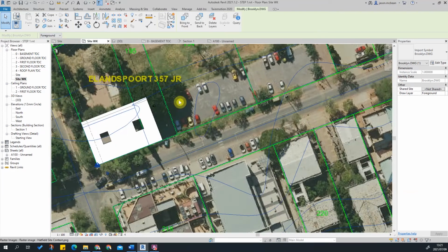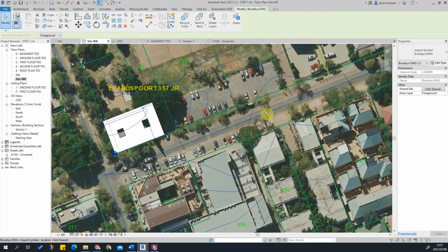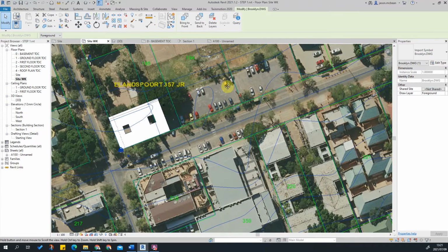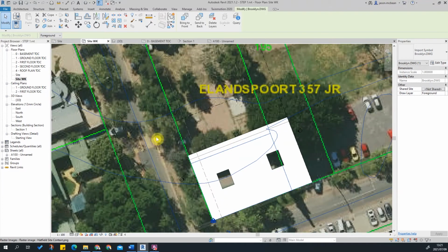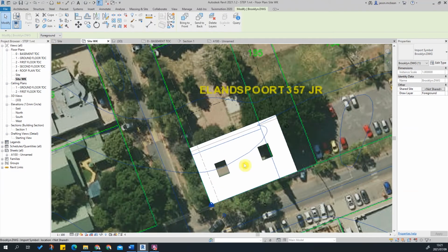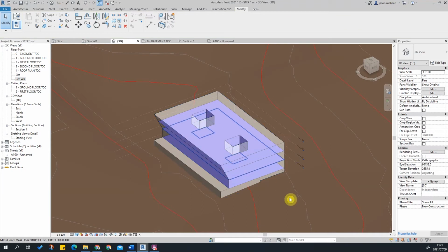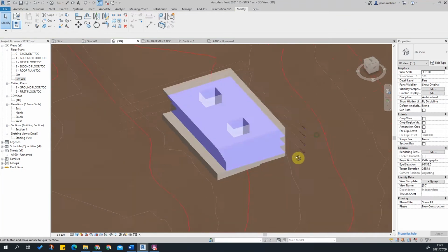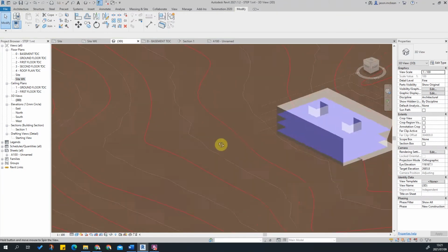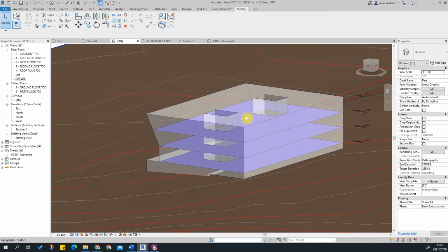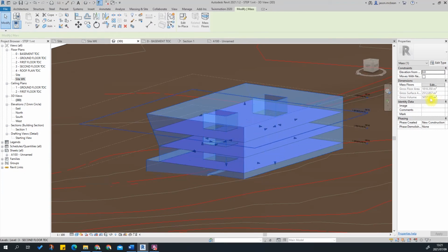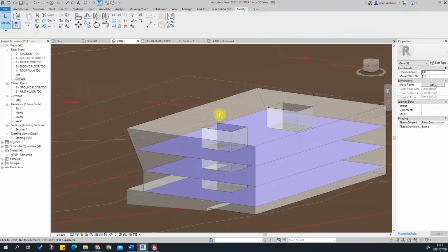But here we're going to start establishing the parking area. Okay, and we're going to start establishing the access to our site and how the back of our site will work. I've used a mass in this instance, so I've got two options. By now you should all have a mass of your design project which you can use, so that's exactly what I've done. I've created a basic mass. The reason why I've created a mass as well is because it will give me the gross volume and floor areas. Okay, because you're going to need these values later on when we do our calculations.